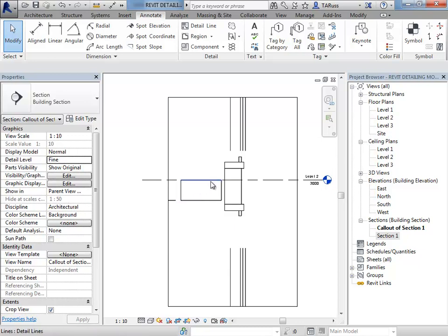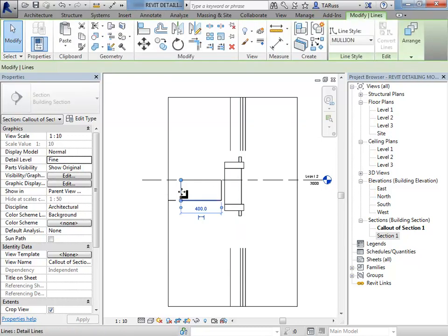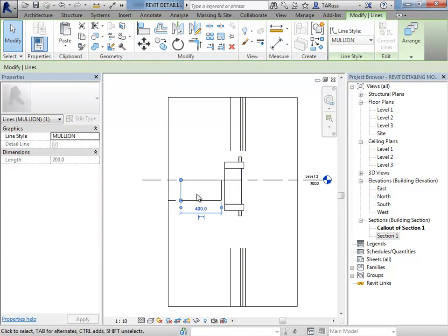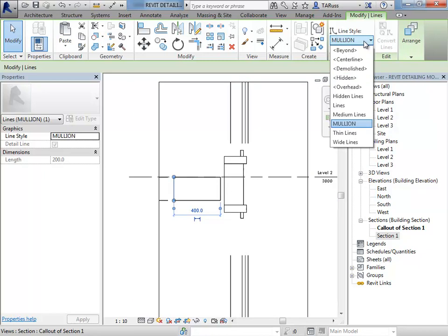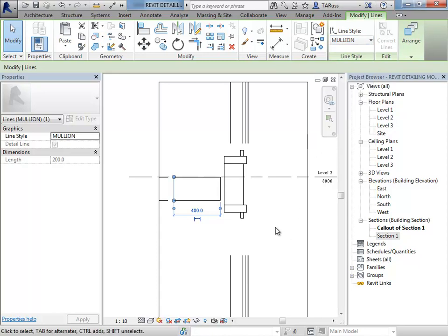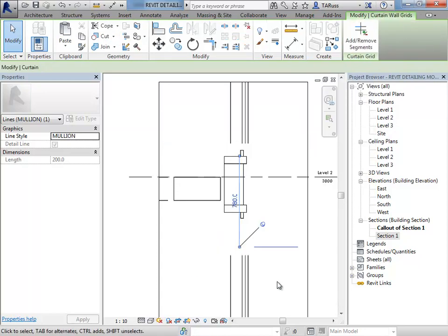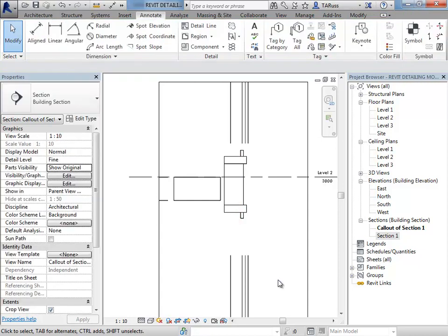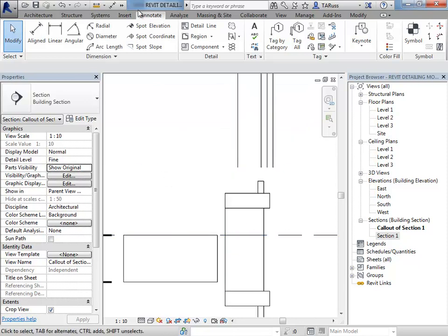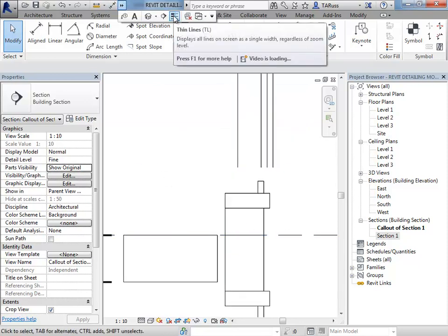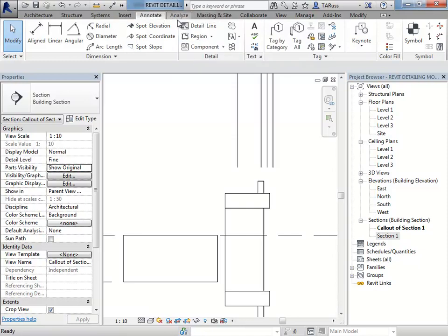Once you've done that, just sort of as a final matter of finish, all of these lines here in Revit, you can see they still kind of maintain some of their information because we only did a partial explode. So what you'll want to do there in order to set up line weights and such, remember that if you hit TL in Revit, it'll kind of simulate those line weights on screen. That command is also available up here. It's this one right here. So TL just toggles between the thin line weights and then the actual line weights.